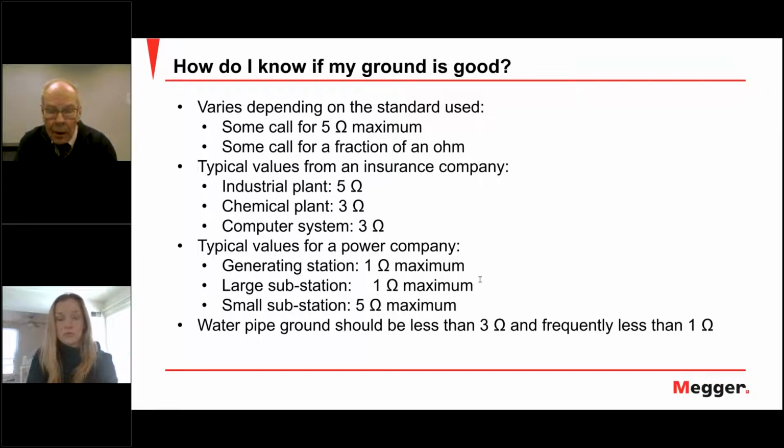I'm not just extemporizing on this or anything. It's actually in there. So that's for safety. And so the 25 ohms is a fairly forgiving standard. If you meet that, you meet code. Okay, you're good, you're safe. But that does not guarantee that your computers aren't going to see noise. You're not going to get pixelation somewhere in a computer-controlled system.